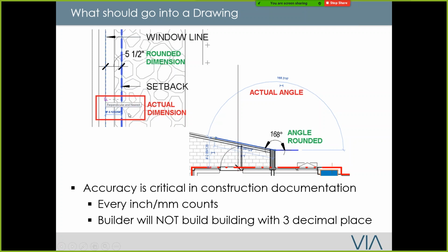Revit can get very picky, and sometimes the wall would not join properly. So I would just say round it up to the nearest. Let's say if it's a 1/2 inch, just round it up to 1/2 inch. You just keep Revit happy. If you do this a lot of the time, Revit would just fail. I don't know why. It's probably the programming itself.